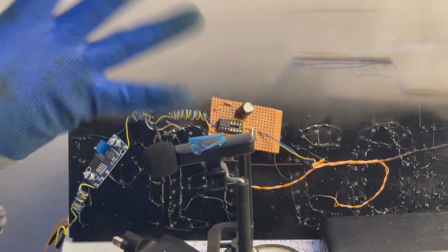Base goes to pin 3 of the 555 timer through a biasing resistor. I use 1K. Then the collector takes the VCC and amplifies the current before sending it to the emitter for our LED anode terminals to receive. That's why if I remove this transistor now, you see that the light will not be bright enough.